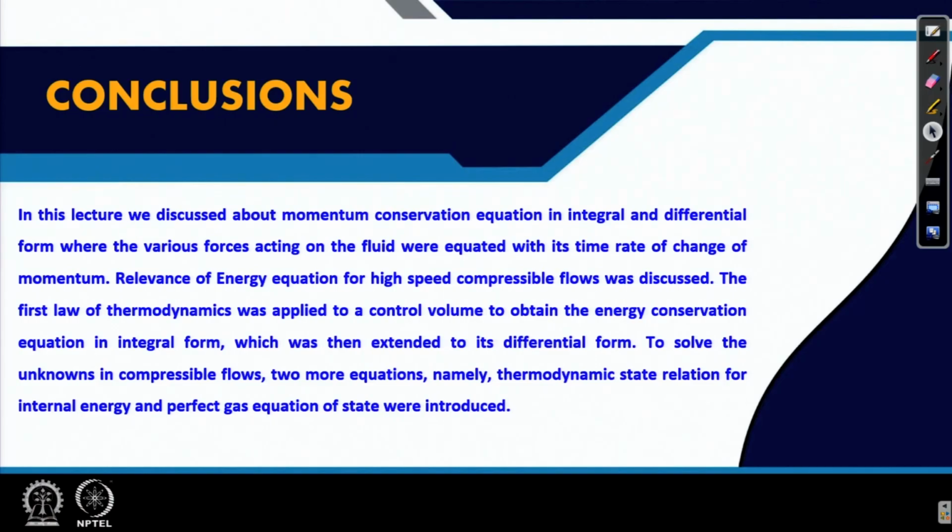Then we extended it to the differential form, which applies at a point in the fluid field. To solve the unknowns in compressible flows, 2 more equations, namely the thermodynamic state relation for internal energy and the perfect gas equation of state, were introduced in order to solve the necessary variables. So, with this we end this lecture. Thank you.